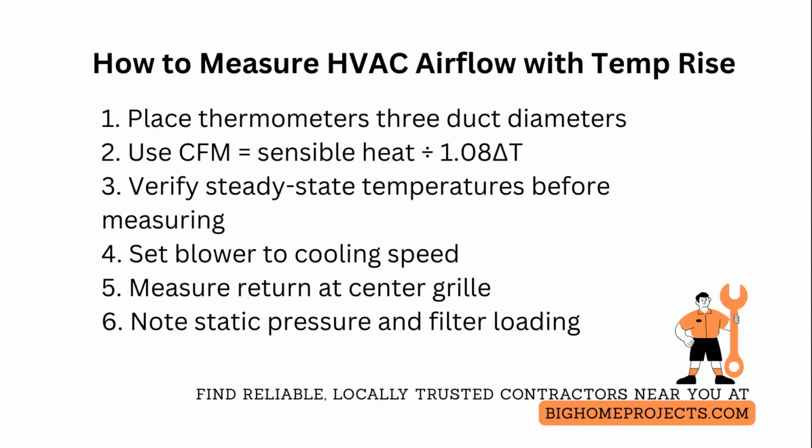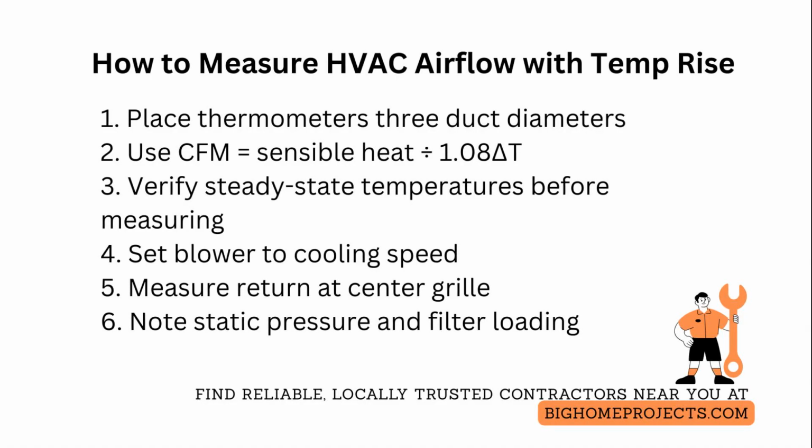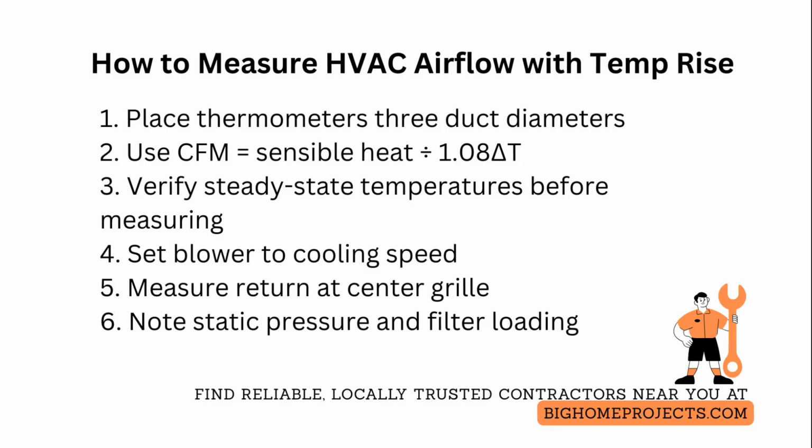To calculate airflow in cubic feet per minute using the temperature rise method, measure supply and return air temperatures with accurate thermistors or calibrated digital thermometers placed at least 3 duct diameters downstream and upstream to avoid stratification.